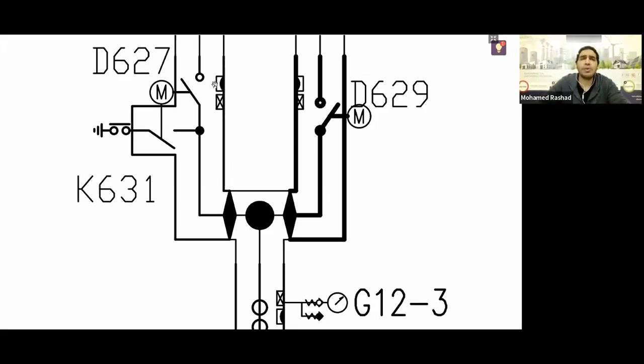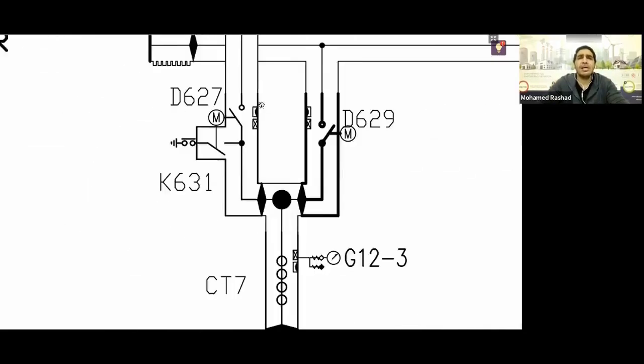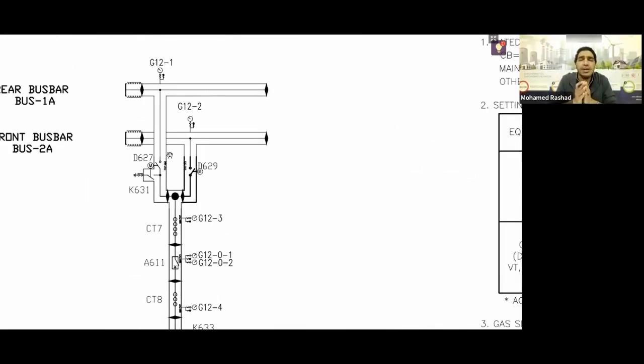Now, the other form is called the ruptured disc. What is a ruptured disc? The ruptured disc is a part of the GIS body. The entire GIS body is made, for example, from steel or aluminum, depending on the current rating. We're not focusing on the construction details here, so I won't delve into that. The important thing is that your body is entirely made of steel, and then you come to a specific part of it and make a part from a completely different material, which we call the ruptured disc.